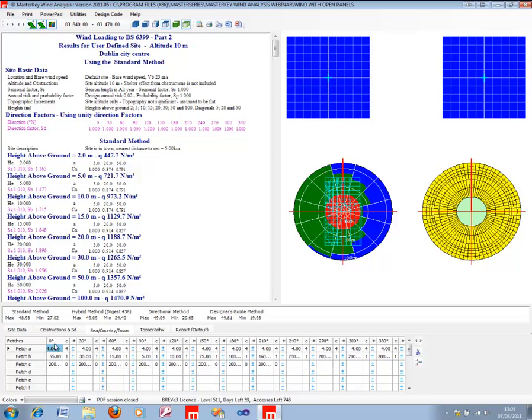So for example, for the 0 degrees, which is the red line here, we've got 4 kilometers to the edge of town, 55 kilometers from our site to the edge of country, and then you generally end up with a 200 value to give you a large value of sea beyond that point. But of course you could actually come back from sea back to country, but we're just going for sea for an infinite distance there, which doesn't affect anything else. So that's all those values inserted.